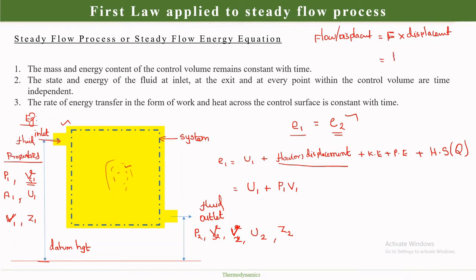Force is pressure into area, so pressure into area into displacement, which I call L. Area into length is my volume, so pressure into volume is my flow energy.